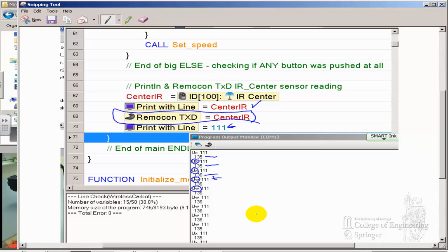Okay? So the take-home lesson is, when you TXD it, it really sends out a 6-byte packet that has your data in it. It chops it up a certain way and sends it over. That means in order to do it properly, whoever receives on the PC end better know how to take that packet apart, reassemble the right data, and print it out. That's the purpose of the Visual C program on the PC that we're going to look at next, because it has to do that.